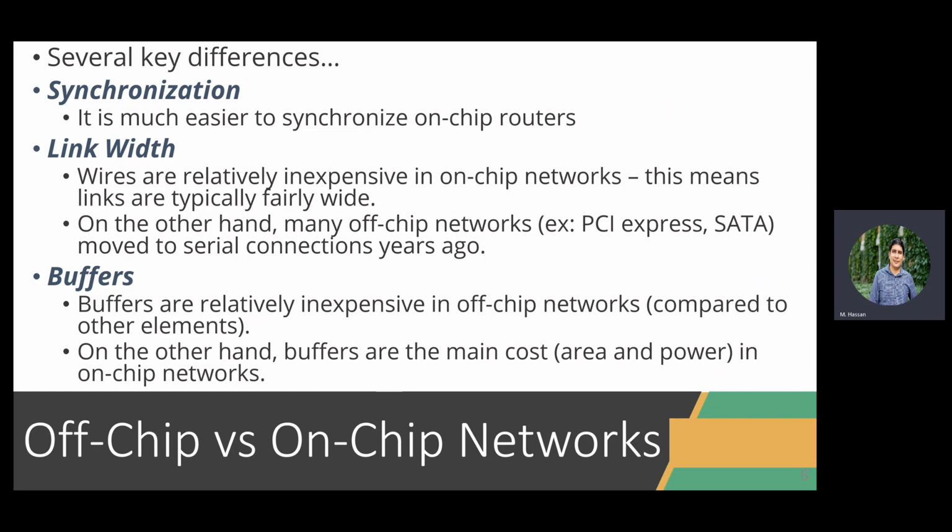An off-chip network, for example, is in fact an asynchronous network. What do I mean by this? What you do is completely independent of the other homes, as in the internet or other countries. Something that's completely federated, everyone is doing its own thing. There is no need for synchronization. Why a network on chip? All of this is running on the same chip, being fed by the same clock tree, the same clock. So in that case, all of them are synchronized.